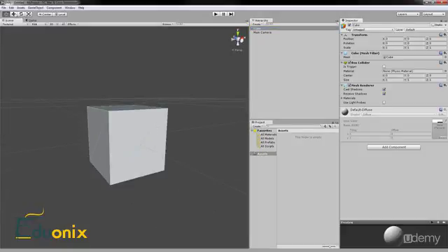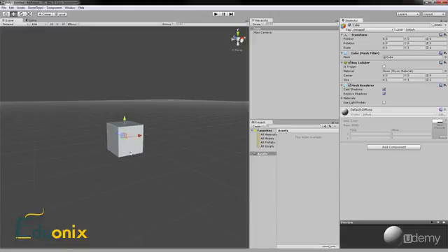This next tool is the translate tool. This allows you to move an object in 3D space. I'm going to zoom out a little to show you this. You're selecting on an object and you have these 3 arrows. Each of them moves your object in a different axis. This moves it in the x-axis. That's the red arrow. The blue arrow moves it in the z-axis. And the green arrow moves it in the y-axis. And once you click on an arrow, it changes to yellow and you can see which axis you're on.